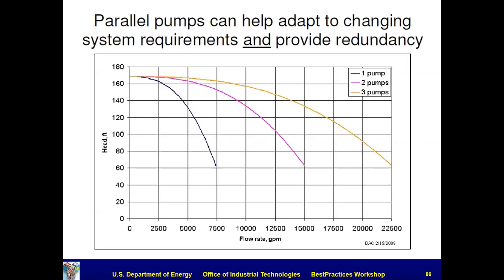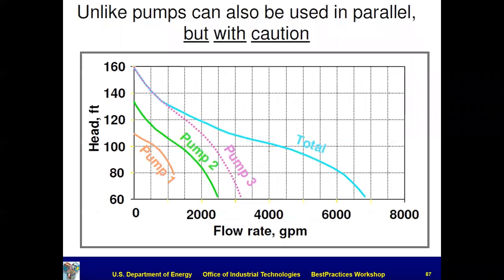And then I put my system curve on that. I just have one system curve. And wherever the system curve crosses each one of those lines tells me where I would operate with 1 pump, 2 pumps, 3 pumps, 4 pumps, however many pumps I want to turn on. That's kind of how we go through the analysis. And we'll see more of that here shortly.